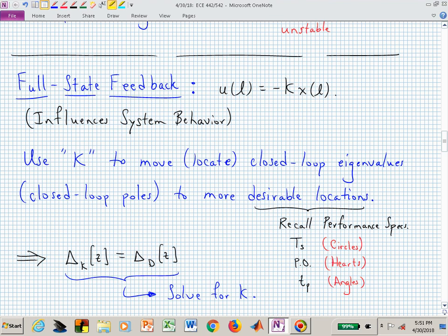When zeta is equal to 0, that says no damping. Where do you think we would live with our desired poles if we had 0 damping? If we had no damping, nothing damps, then where are we living in the z-plane?